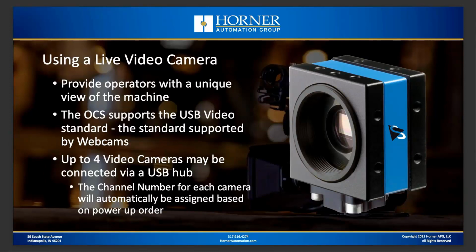Now, in addition to playing back video from an MP4 file or similar video file, you can also use those same products for displaying live video to provide your operator, for instance, with a unique view of the machine. So you might have a scenario where an operator is at one section of the machine, and there is a key location in the machine that the operator just can't see very well for whatever reason. Maybe it's inside of a pinch point and out of their view. Maybe a part needs to nest in a fixture, and if the part isn't nested properly, that can cause problems. So by putting a USB video camera in that area, you can provide a window on the screen of the OCS that shows the operator what they can't see on their own, based on their location or whatever the situation might be.